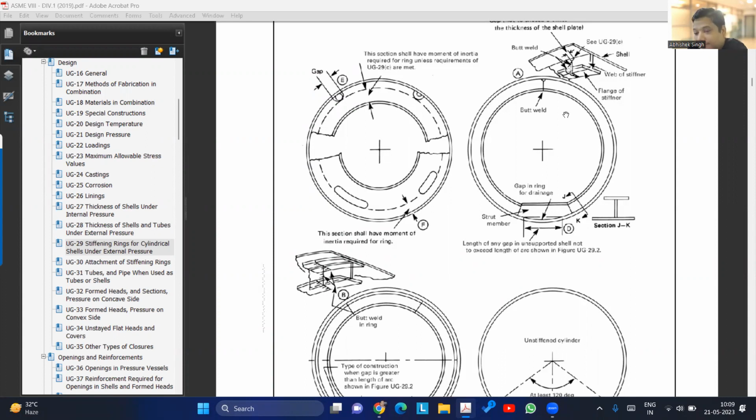Okay, so now there is a stiffening ring. So definitely there is no diameter difference, if it is already welded. Yes, sir. But the only thing is that on the top side of the baffle there is a gap, I mean 10% gap. My ID of the vessel is 4000. So there is a gap at the top. Does not matter, it can be anywhere. My question is whether we can use it as an internal stiffener, and if yes, then how much arc we can assume?